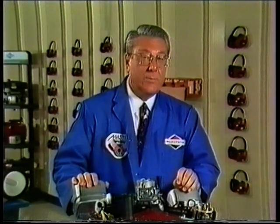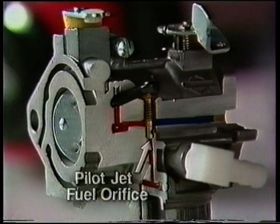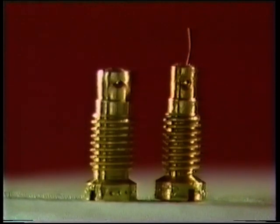Here's a troubleshooting tip for float-style carburetors that have pilot jets. Even seasoned veterans will appreciate this tip. A performance problem can result when the pilot jet fuel orifice is completely or partially blocked. This can be caused by debris and in some cases by fiber strands from non-original fuel filters.